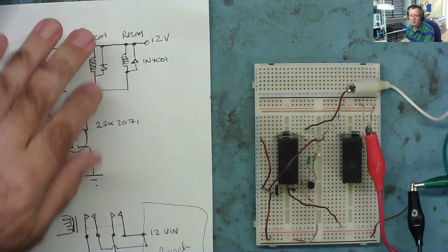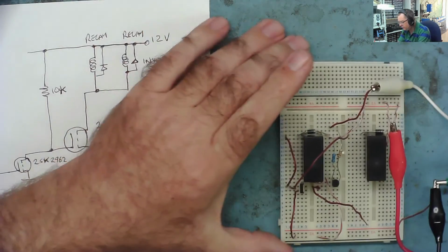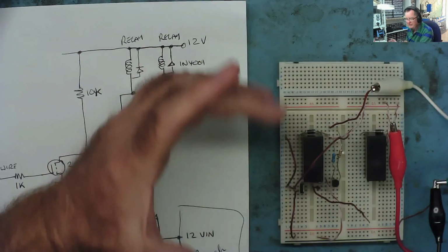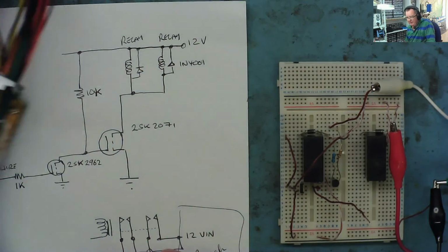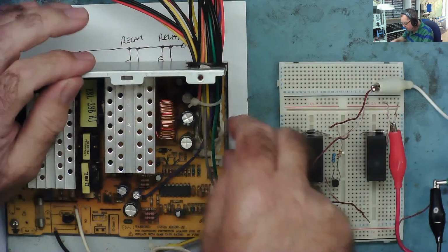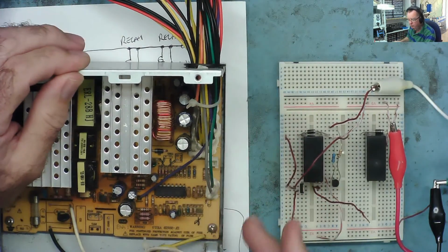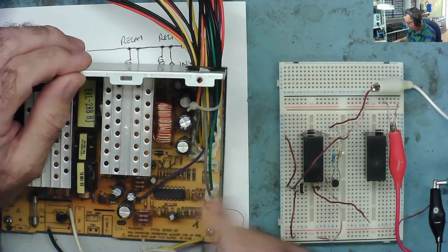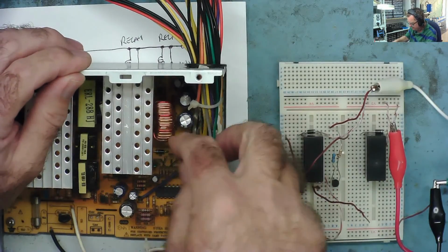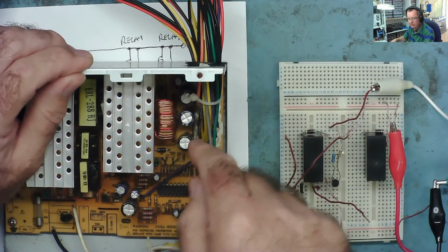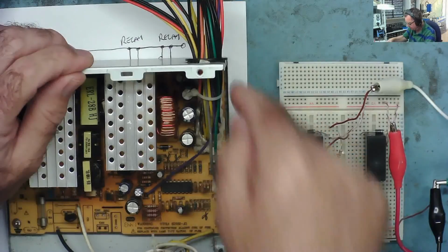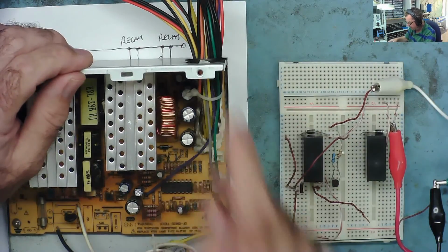So that's working. So what I'm going to do now is put this circuit together on a bit of Vero board. I'm going to cut or solder to the board one way or the other. Some thick wires going to the relays. I'll disconnect this lot. Under here I might just cut the tracks to disconnect them, and then solder in the 3 wires coming from the relays.